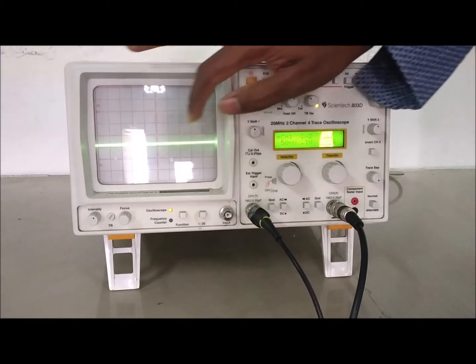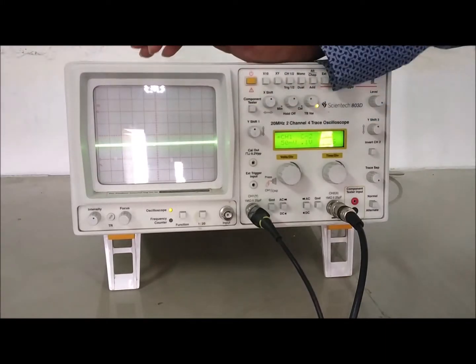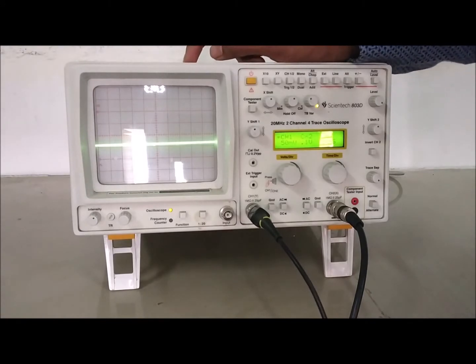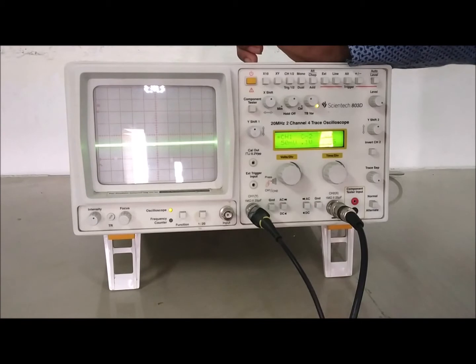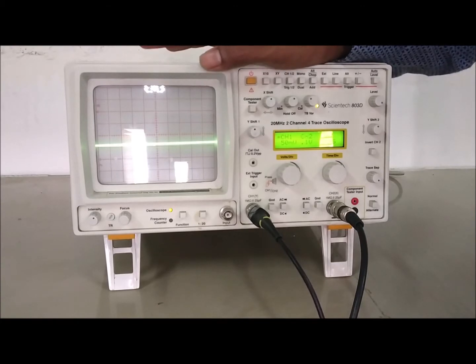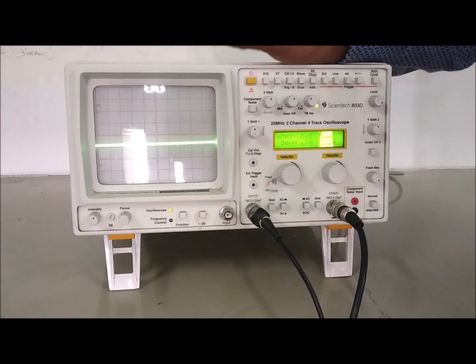If I take this as the x-axis and the midpoint as the y-axis, these two axes we are using to measure the signal. What parameters do we measure? We measure the voltage, which is nothing but amplitude, along the y-axis, and we measure the time period along the x-axis, or we can also call that frequency. Two important parameters we measure on the CRO: one is amplitude and the second one is frequency. If we measure these two parameters, then we have measured the signal.